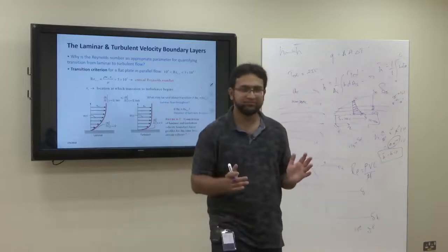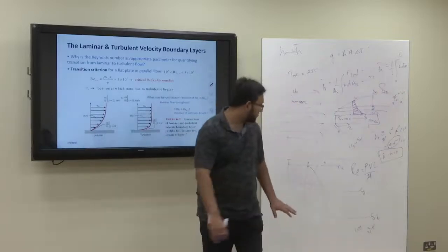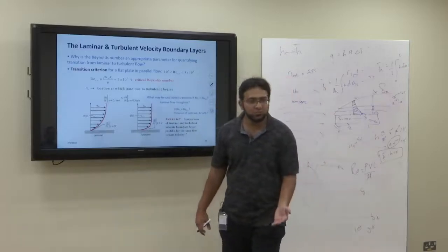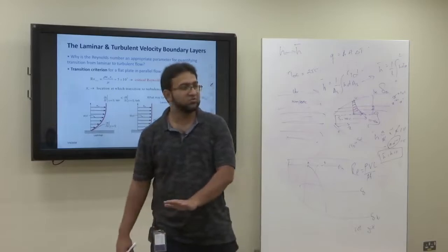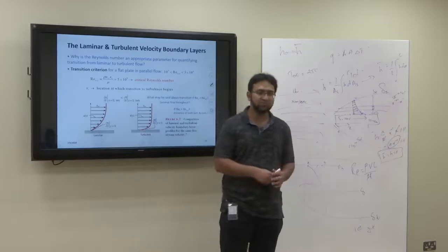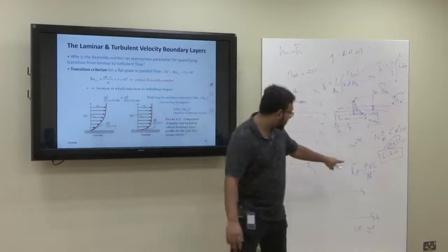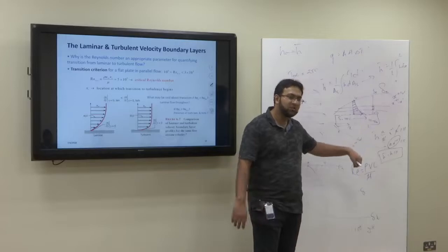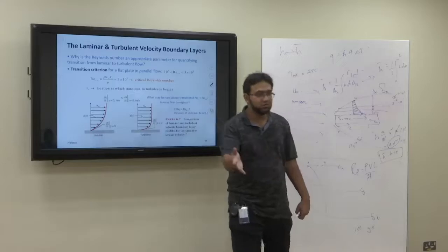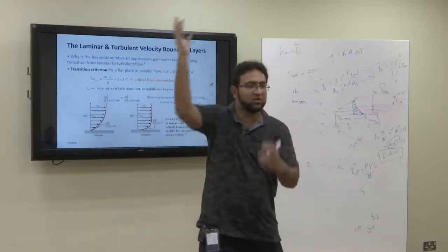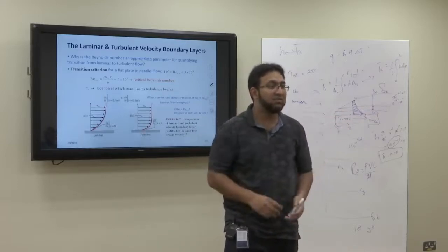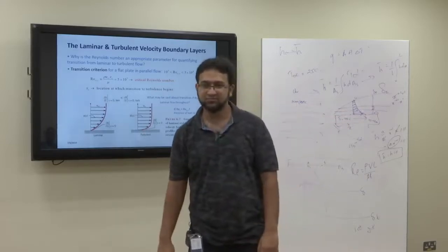Is it clear? So these are the parameters which determine whether the flow is smooth or not smooth. Okay, not necessary. Sometimes the velocity is high. Yeah, many times what happens is that if the velocity is very high, the Reynolds number will be high. If the velocity is less, the Reynolds number will be less. But it's not just the velocity. For example, lava. You know, from mountains, lava comes. Do you see the speed of the lava? So slow. But lava is highly turbulent. It's not smooth.